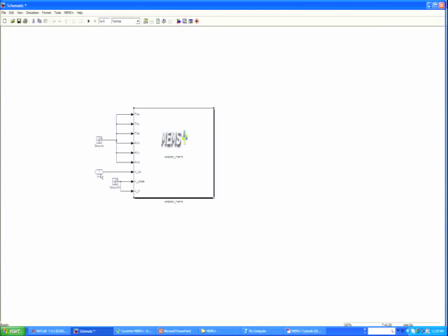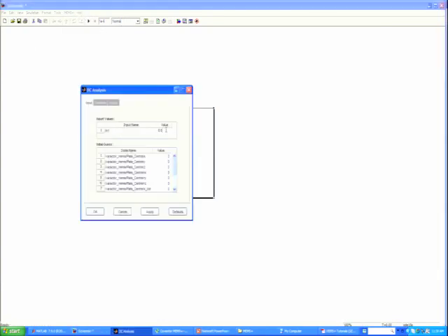So I'm going to get a curve as the voltage goes up. I'm going to see the device starting to pull down. So I go to DC analysis. I say I'm going to start from 0 volts. I'm going to go in steps of 0.1 to about 15. I think I've defined that right.